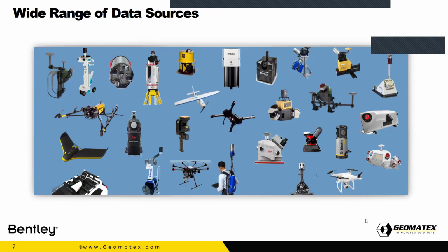And then you could go to a simple Phantom 4 or Phantom 4 Pro drone, which could cost you less than $1,800, and you could still get a very, very accurate 3D model, but you still have to do some ground control points. Or if you're lucky to get the real-time kinematic version of this drone, you will be doing a very good job with a very limited budget project. So we can see mobile mapping systems, we can see fixed wings with belly landing, we can see some cameras flying in the air via some dedicated drones. So the sky's the limit.